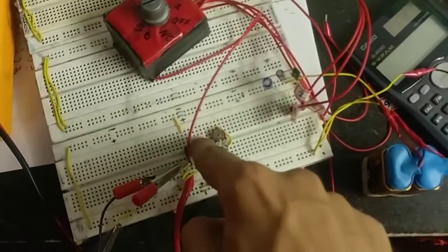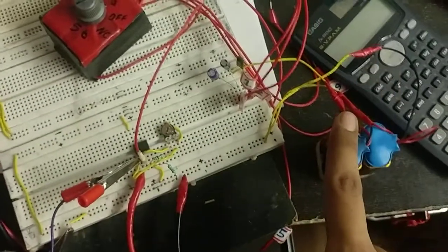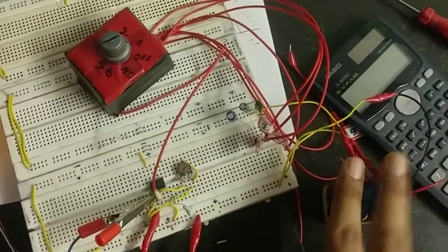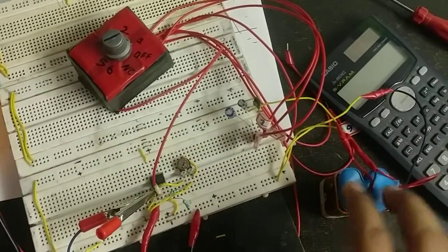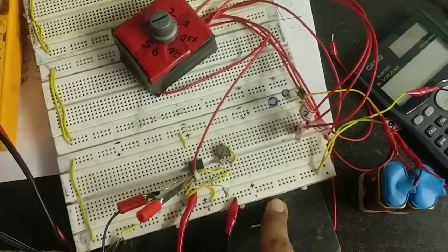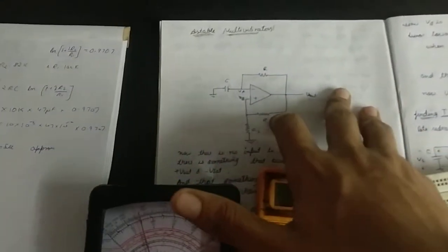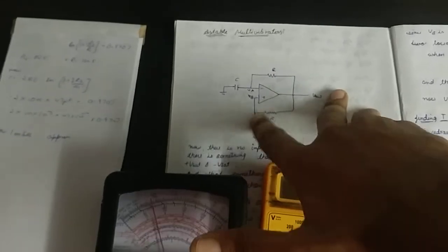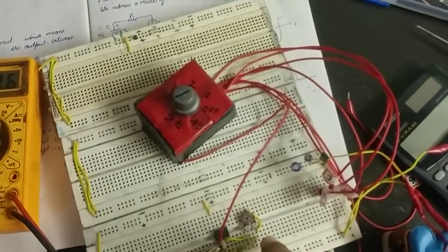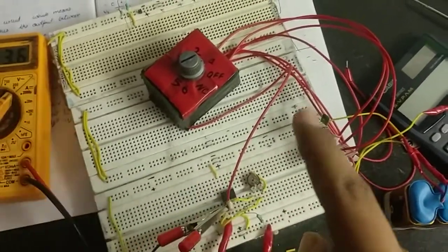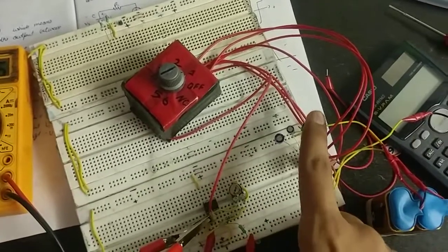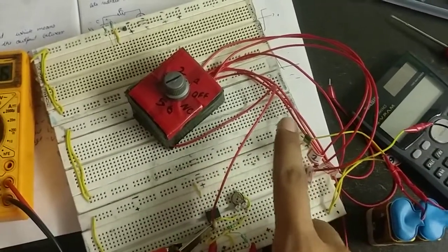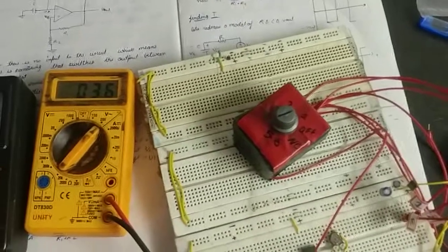This is an LM358 operational amplifier. I'm powering it using this dual minus plus 9 volt supply using this battery bank. I have chosen R1 to be 100k and R2 to be 82 kilo ohms, because I want 50% duty cycle. That's why I've chosen these values. And for R, I am using a preset that is max 10 kilo ohms, and I'm using C of three values, that is 10 nanofarad, 47 microfarad and 220 microfarad, just to show you a little bit of difference.